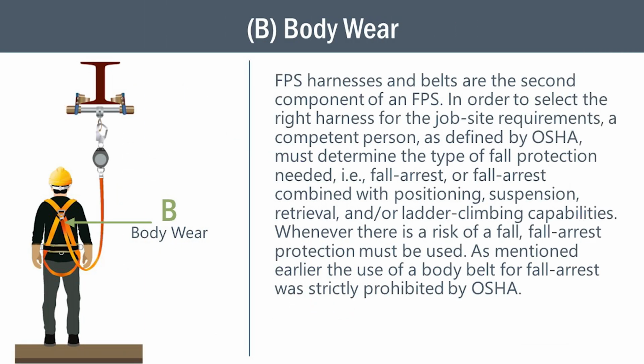And of course, your body wear. There's different types of manufacturers and things of this nature. There are weight limitations on some of these. So if you have people over 300 pounds, you might want to talk to the manufacturer about buying a special harness for that person. Because if I remember correctly, these systems are set up for like 300 pounds and 10 pounds of weight from other things, like tools and things people may utilize in their job. Okay.